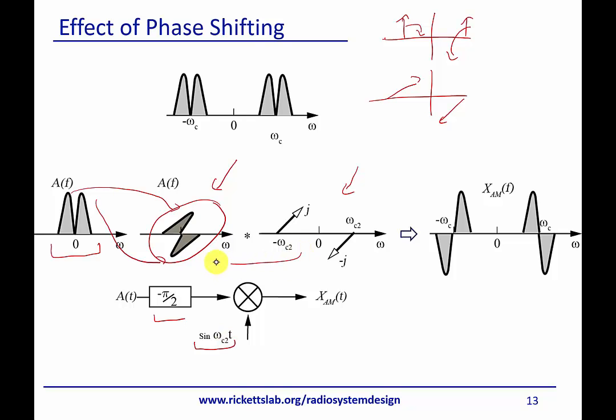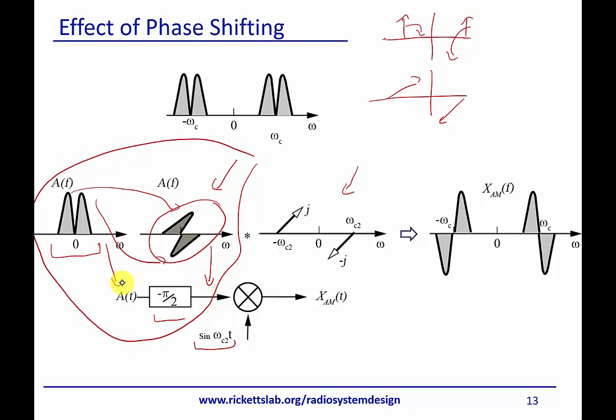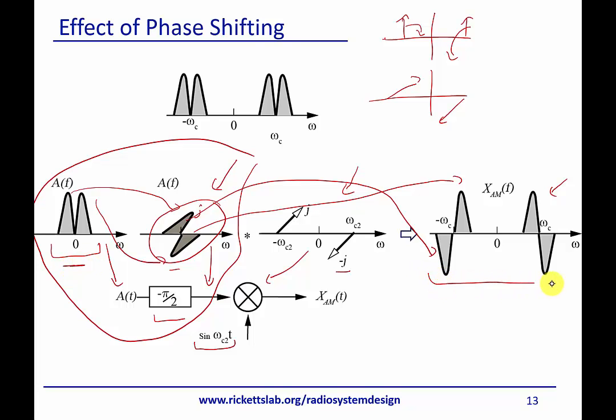Okay, these two have zero connection with one another. All right, so let's be very clear about that. This is what we have here. This is the signal that comes out here. This is the signal that goes in. This is all about this multiplication. The reason I do that is if I have this being equal to j, and j times j is what? It's minus 1. And so we end up with minus 1. And now I have minus j times minus j gives me a plus. And so this ends up here. And likewise, if you follow through, I get this pattern here. And so now I've created a version of this spectrum that is just like this.